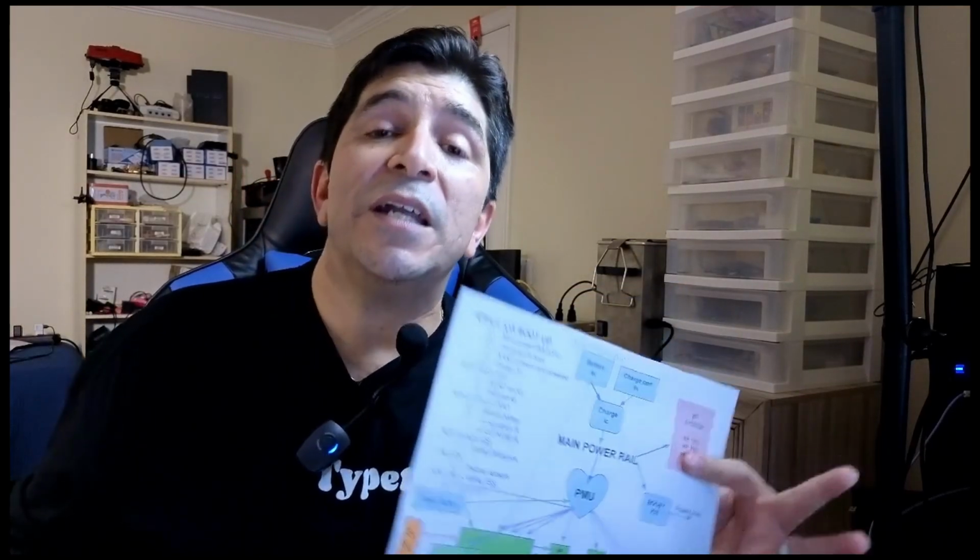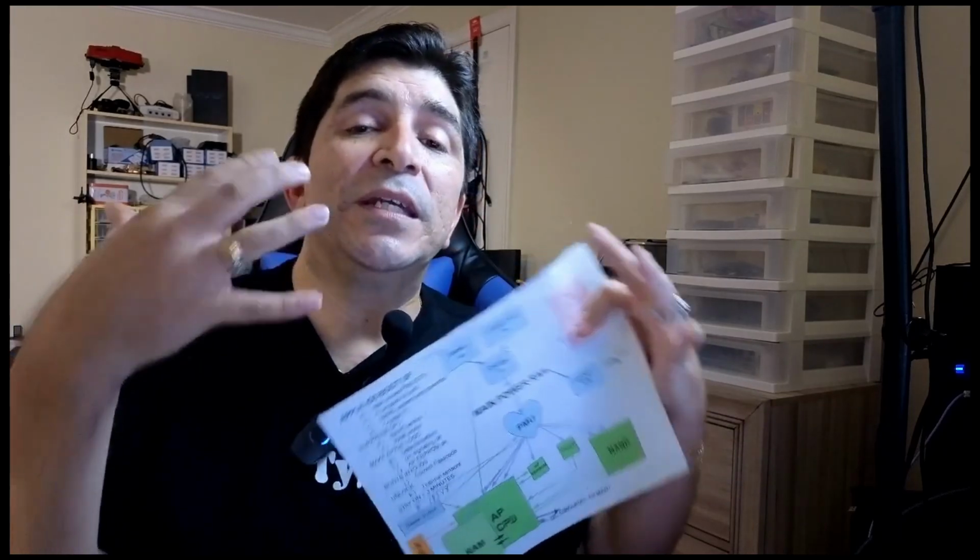So if we were designing a phone, that would be the starting place that we would need to design into the product that we're making. And she also gave us an example. If we were to get a battery, okay, it's a 4-volt battery, and we were to test it, if it said it was 3.8, that means that battery is low. A full battery would actually test around 4.2, 4.3. That is a full battery.